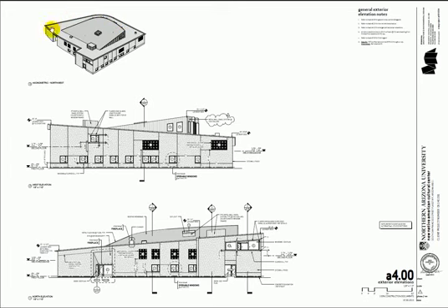Okay, this building has curves and it has sloped roofs. There's that little elevator pop up where we're seeing punched windows. So I now have traversed the whole set of drawings, and I have a feel for what's going on. It looked like back in this area by the elevator we had a little mezzanine. Otherwise, it's for the most part a single-story building, and that helps me understand the structure.